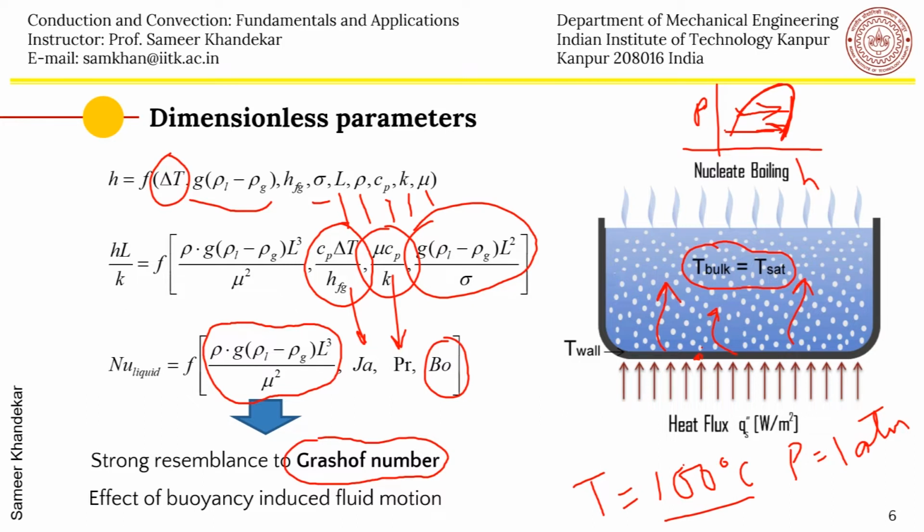In case of boiling, the bubble wants to go up because of buoyancy, and the viscous forces of the liquid are the ones which are posing the resistance to this motion of the bubble. So you see the Nusselt number now depends on the Jacob number, the Prandtl number, the Bond number, and this Grashof-number-looking type of number, which is also called the buoyancy number, or the effect of buoyancy-induced flow motion, is what is captured by this number. So there are four basic non-dimensional numbers on which nucleate pool boiling will depend.